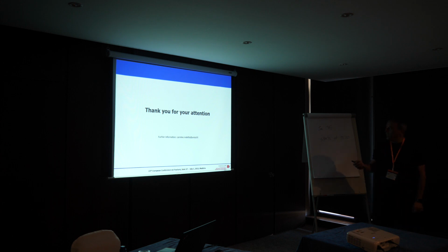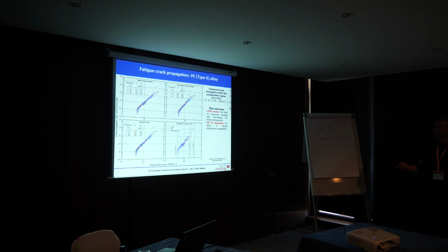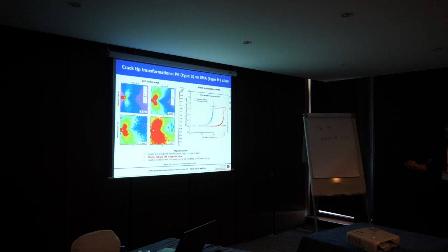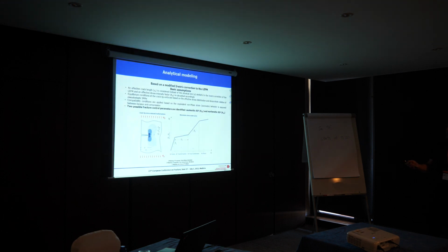The model you mean? So I saw some experimental data, but I was wondering in the fatigue crack growth curves, so later on. The model is just a model to estimate the effective stress intensity factors. So we use the model to recalculate the stress intensity range that are fitted in the fatigue region.